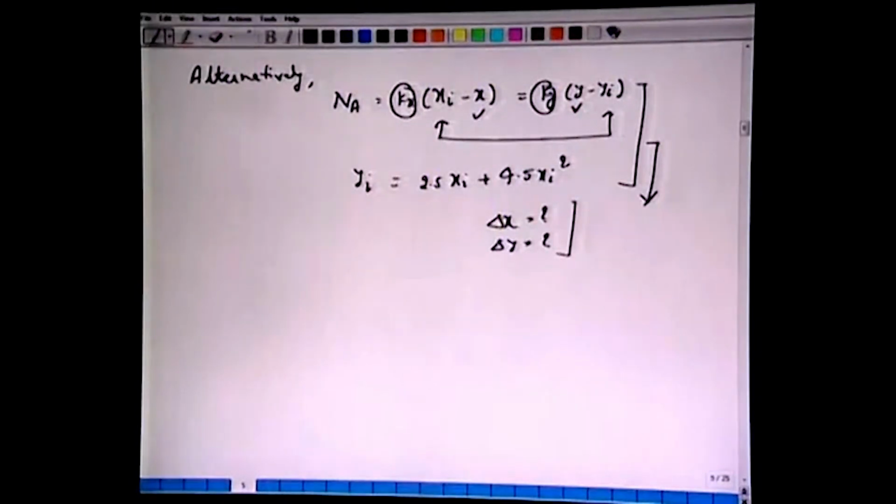The more important thing to note here is that the number of transfer units can be calculated graphically as well as analytically. If you recall, for dilute solutions we have a very simple expression: dy over y minus yi. Again, y minus yi is the same quantity which you calculated here at location 0.02. So y minus yi is the driving force. If you are supposed to integrate dy by y minus yi from y1 to y2, we are supposed to draw several of these parallel lines of slope minus kx over ky.